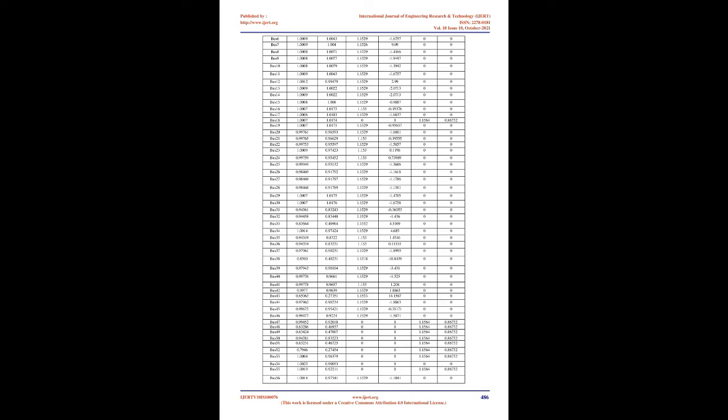Therefore, a corrector step with a fixed voltage at the monitored bus is applied to find the exact solution. As the voltage stability limit is reached, to determine the exact maximum load, the size of load increase is reduced gradually during the successive predictor steps. The computational procedures involved in continuation power flow methods consist of predictor and corrector steps, as explained as follows.